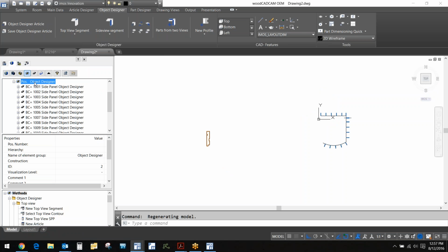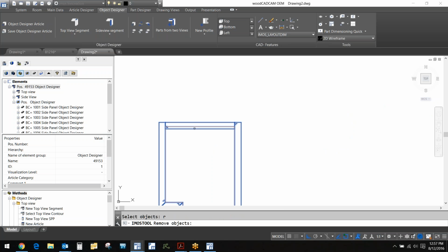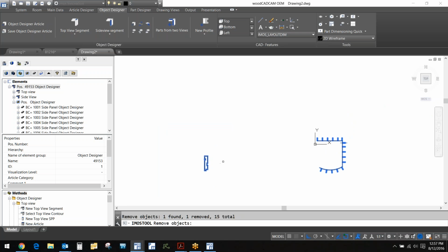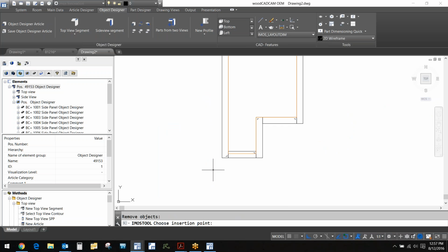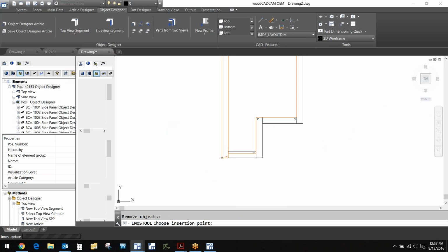I also want to work on this one more time and make parts from 2 views. I'll take all these sectional views and this polyline path, and I'll remove from my selection this original polyline and say that I want to make all of the parts for this. So it's going to extrude all of those parts, and I just gave it the location that I want it to know in reference to the polyline that I created, so that everything fits exactly as it should.